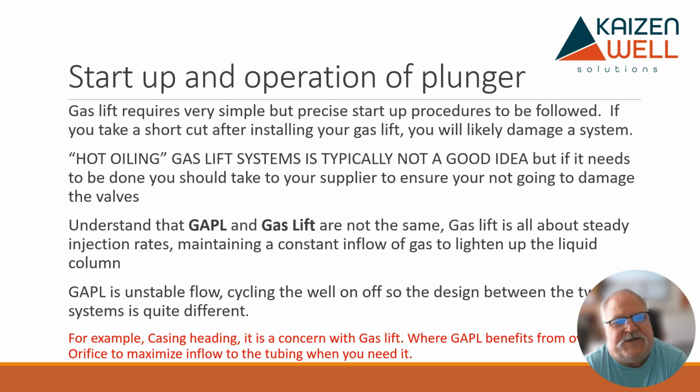Startup and operations of a plunger. One of the big problems we'll see is guys will do things like hot oiling. It's typically not a good idea, and there's really no safe rate that you can pump liquid through a gas lift valve. It's pretty low before you're going to start damaging it. A lot of guys are hot oiling these valves or pumping hot water down, and basically they're damaging valves because they're pumping too fast, too aggressively.